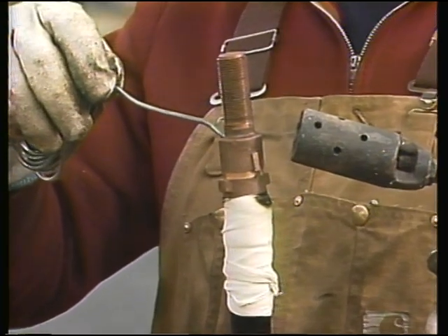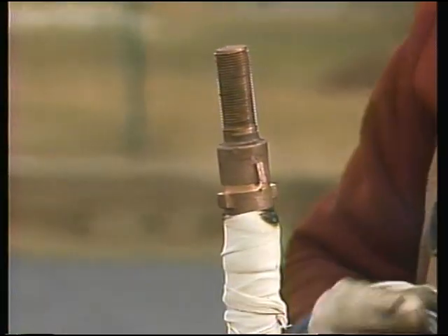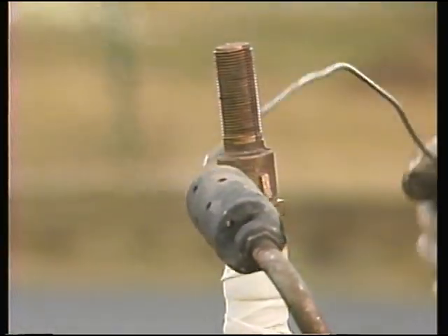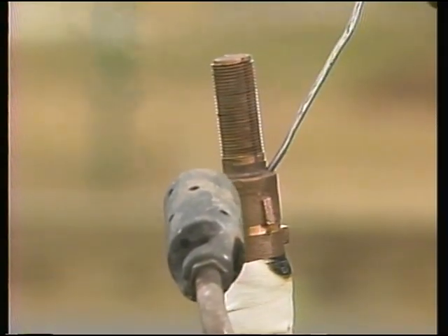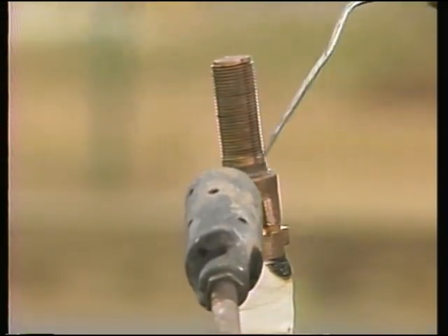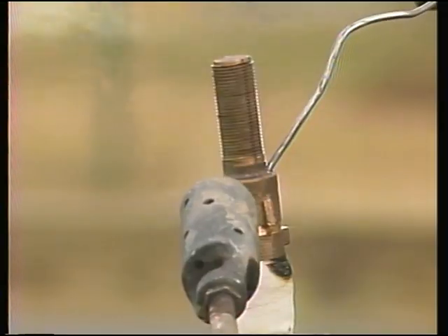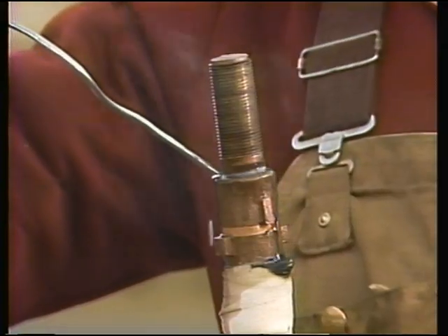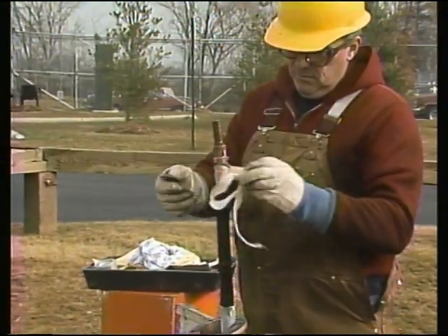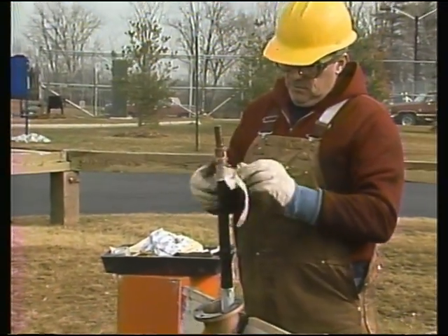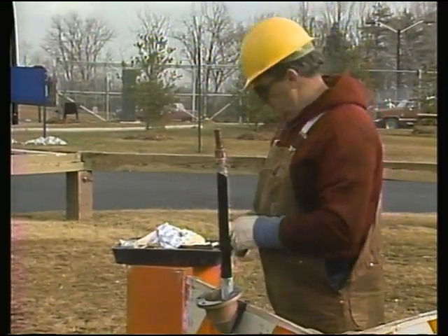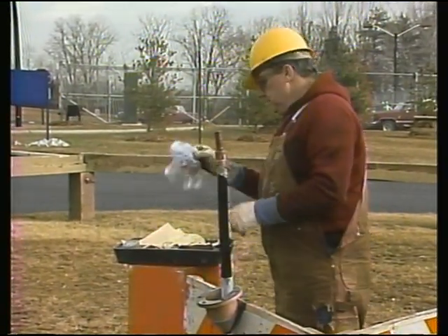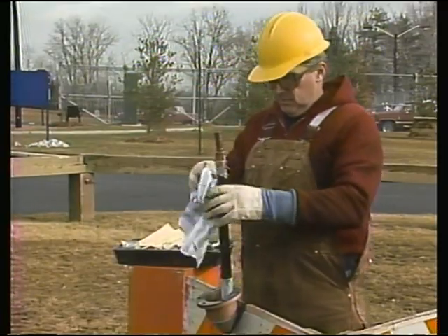The heated connector and conductor cause the solder to melt. The melted solder runs down inside the connector and between the conductor strands, forming a solid metal mass. When the connector will not take any more solder, the soldering is complete. After the solder has cooled, the workman removes the fire-retardant cloth and wipes the area around the connector to remove any excess solder.